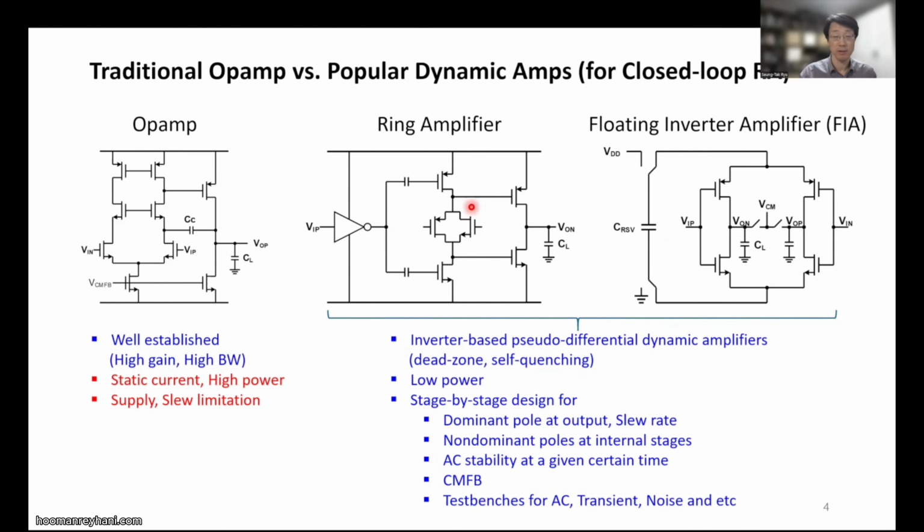And because they are pseudo differential circuits, common mode feedback implementation will be an issue. Even though floating inverter amplifiers theoretically don't require common mode feedback, when the parasitics are considered, we need common mode feedback. We will discuss more about these, like transient simulation and noise considerations.